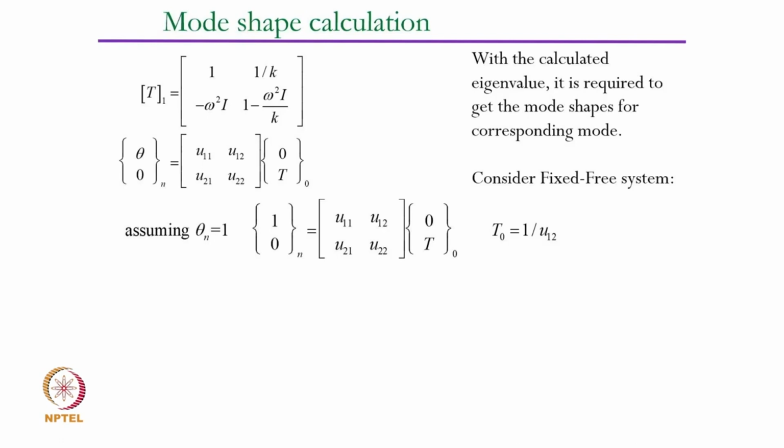Relative to one particular deflection, how other elements are deflecting in relation to that, what are the relative displacements or deformations in the vibratory system. That is what our eigenvector is all about. For example, if the shaft is flexing, and if this is treated as maximum 1, then how much is this, how much is this, how much is this, that is basically your mode shape.